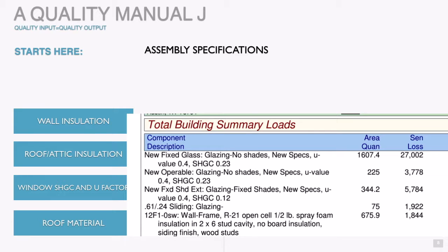So for example, we see this says U value, it should say U factor and SHGC. Those two inputs can have a pretty significant impact on the results of the loads, especially if you have a lot of them. You want to make sure that the U factor in particular reflects the actual windows which are going to be installed. So if you have site-built windows that may not be thermally broken, that's something you're going to want to pay attention to and make sure you get right.